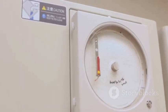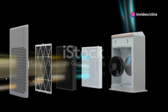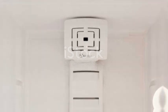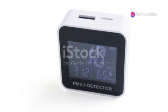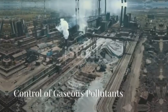After that, we have fabric filters or bag houses. The principle involves using fabric bags to filter particles from the air. Air passes through fabric bags that trap particles on their surface. Finally, there are electrostatic precipitators, or ESPs. They operate on the principle of using electric charges to remove particles. Particles in the air are electrically charged and then collected on oppositely charged plates.